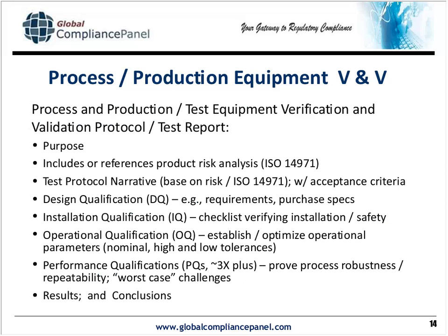Now, when I do a validation document, I start out with an introduction and purpose. I reference the risk document because I'm going to have this as a risk-based document in terms of how far I drill down on various issues. There will be a protocol defining how the test is actually carried out, along with predetermined acceptance criteria. That's a big issue with the FDA.